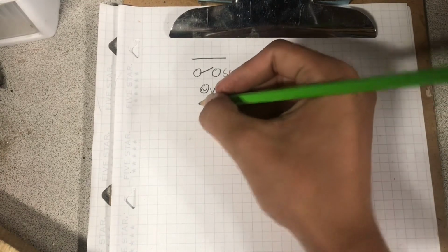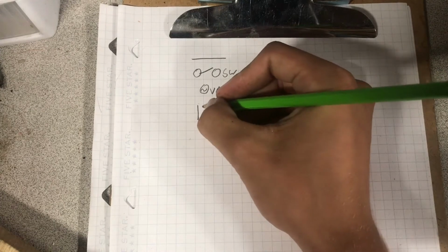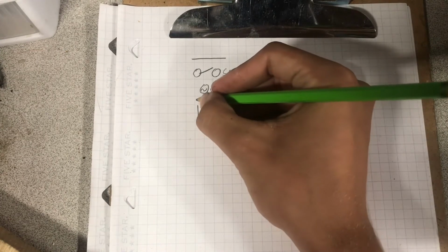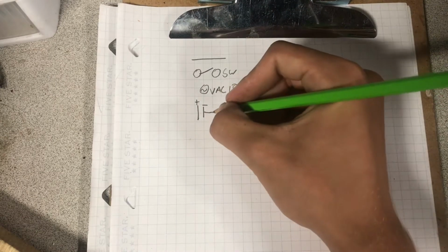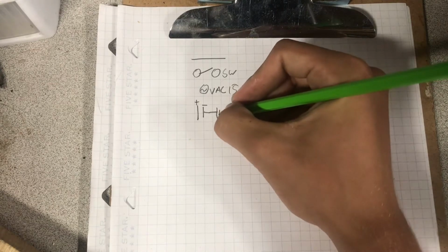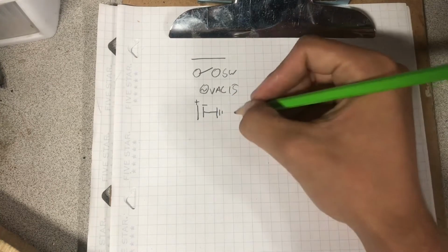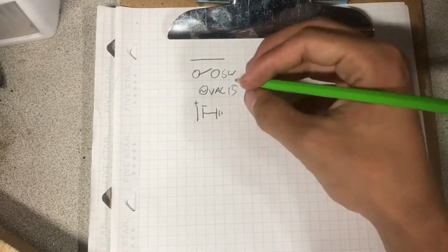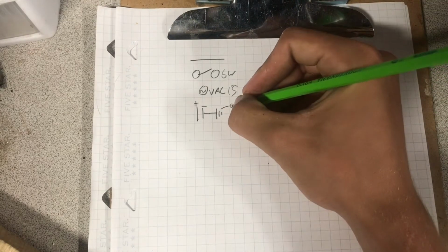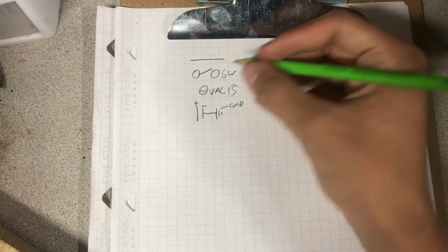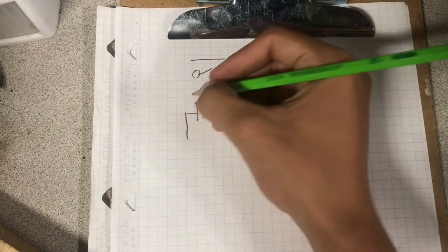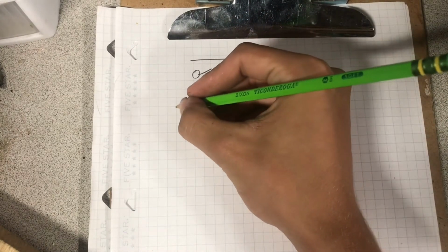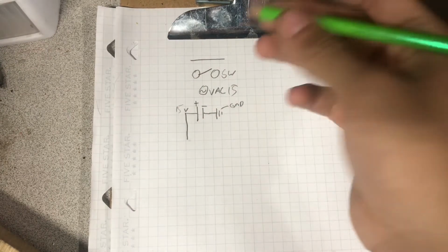Well, we can do a couple of different symbols here. One way you can represent that is you have a negative and a positive, right? This is sometimes referred to as ground. What you might see on some schematics is something like that. That means reference to ground, which means negative on a DC power supply. So let's label that as ground, or GND. This is our positive, and that can come out and do whatever. You would usually put, say, 15 volts again, or 12 volts, doesn't matter.